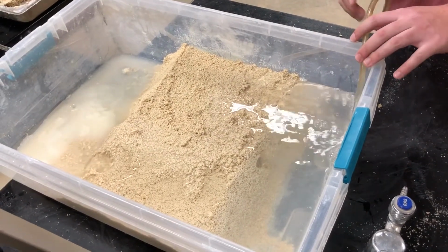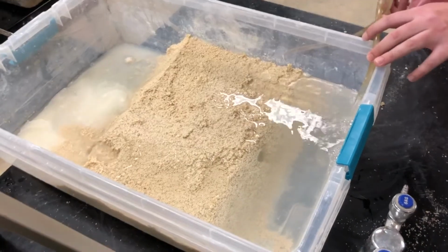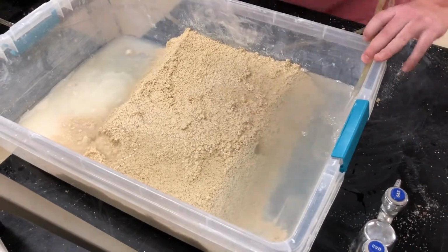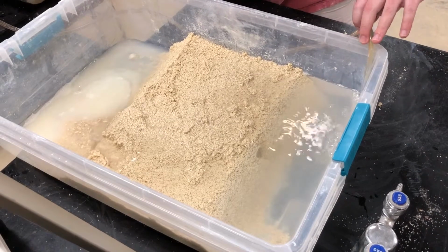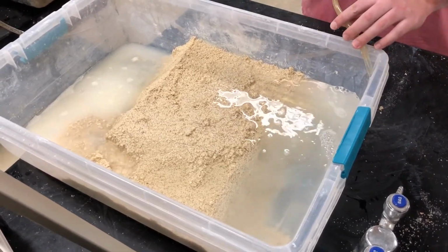During severe rainfall events, debris can become lodged in the culvert and cause reduced outflow or even complete blockage, resulting in water ponding on the inlet side of the embankment, leading to overtopping conditions.